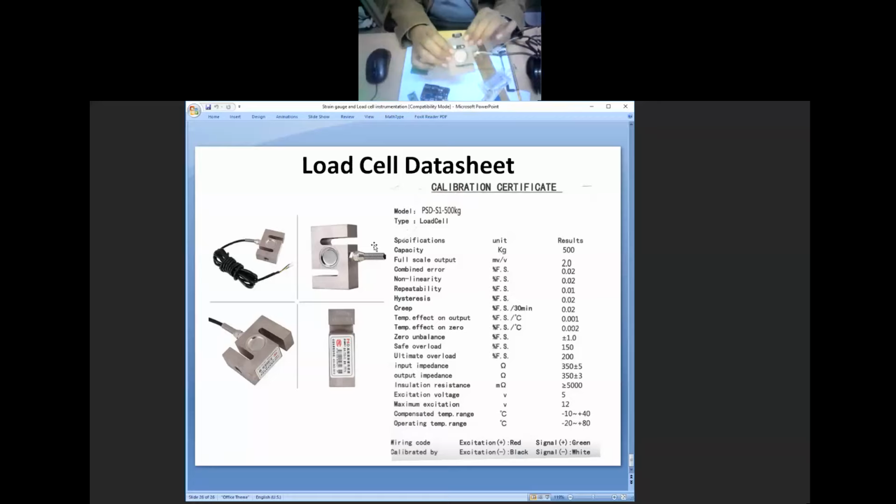This is a load cell. As I showed here, it already has a full bridge arrangement. It means four strain gauges are already arranged in Wheatstone bridge, and all of them are active ones. So full bridge. Remember this circular zone here. All those gauges are here only, placed here.